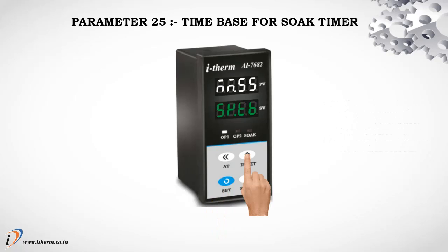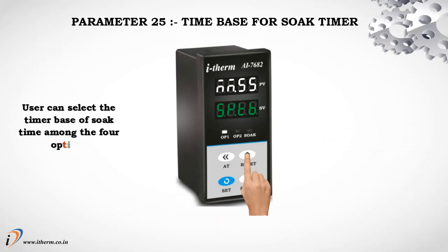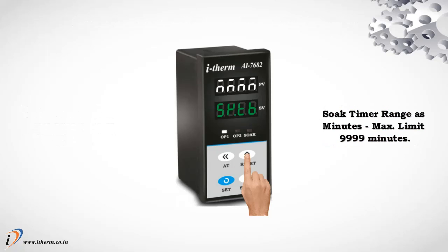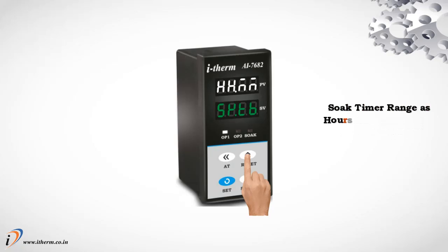Parameter 25, time base for soak timer. User can select the timer base of soak time among the 4 options. Soak timer range as minutes and seconds. Maximum limit 99 minutes, 59 seconds. Soak timer range as minutes. Maximum limit 9999 minutes. Soak timer range as hours and minutes. Maximum limit 99 hours, 59 minutes.